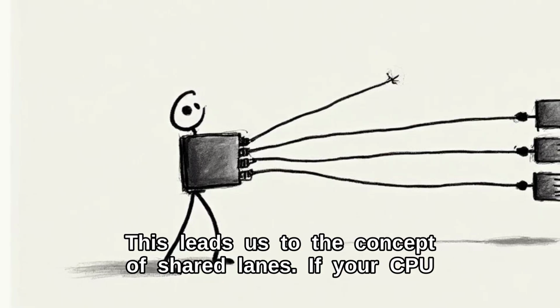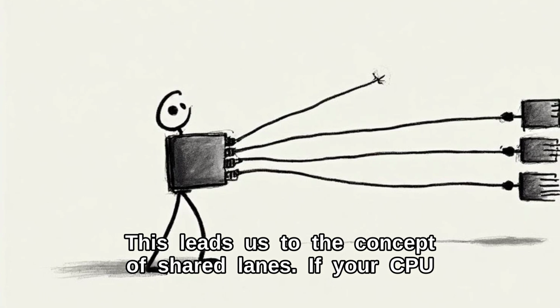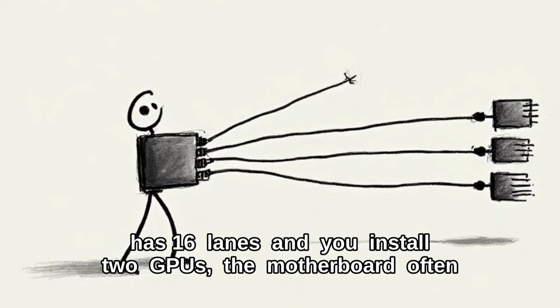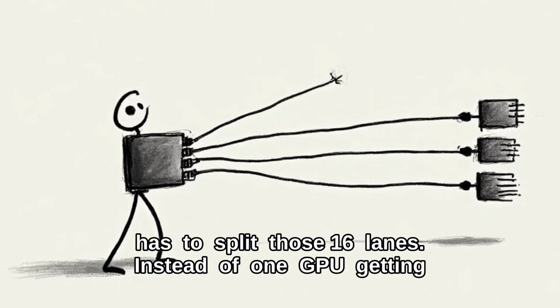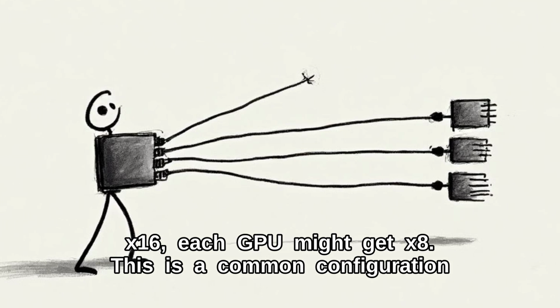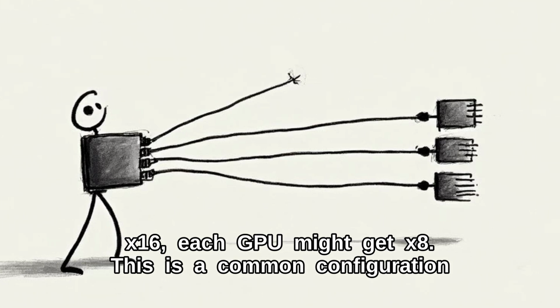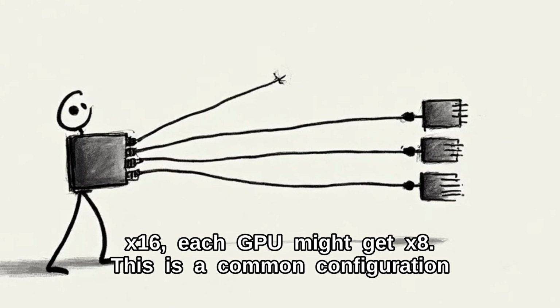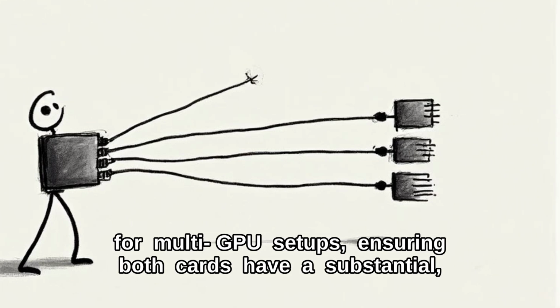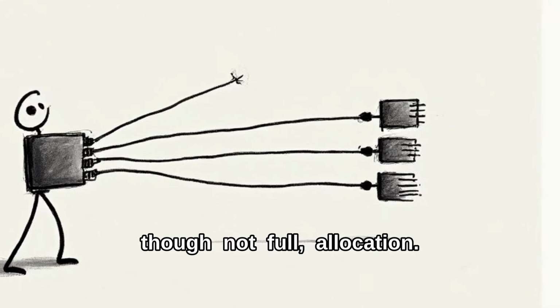This leads us to the concept of shared lanes. If your CPU has 16 lanes and you install 2 GPUs, the motherboard often has to split those 16 lanes. Instead of one GPU getting x16, each GPU might get x8. This is a common configuration for multi-GPU setups, ensuring both cards have a substantial, though not full, allocation.